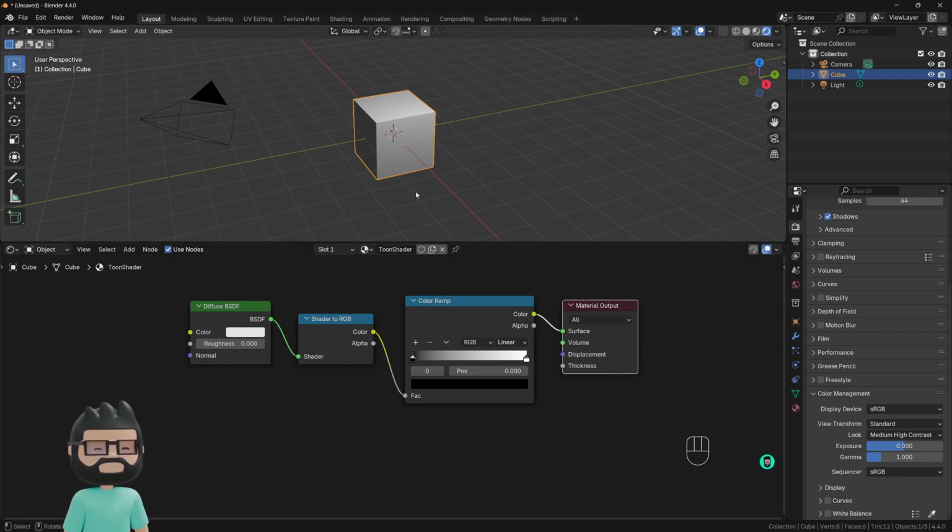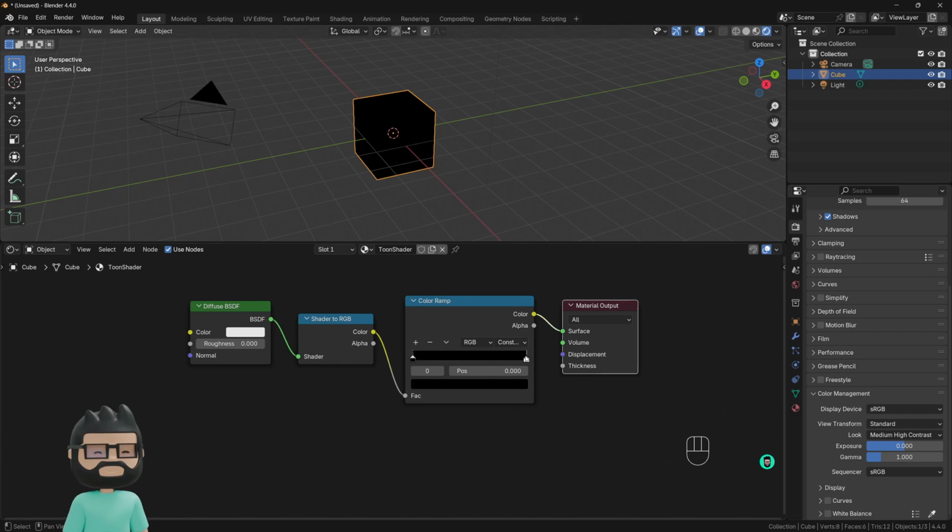But to get the full effect of the Toon Shader, that is the crisp lines or the distinction between colors, we need to change it from linear to constant interpolation. Slide this slider or marker to change where the area or the highlight appears.